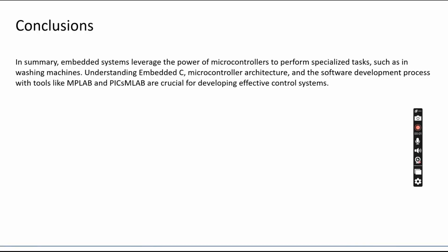Now, after implementing the washing machine, we faced some challenges. Implementing a washing machine controller had its challenges, like real-time tasks. Precise cycle timing required careful programming of timers and interrupts. The PIC16F877A's limited memory means we must optimize our code, avoiding heavy operations like floating point math. Simulating in Proteus helps catch logical errors, and testing hardware step by step ensures reliability. These practices make the development process smoother and more efficient.